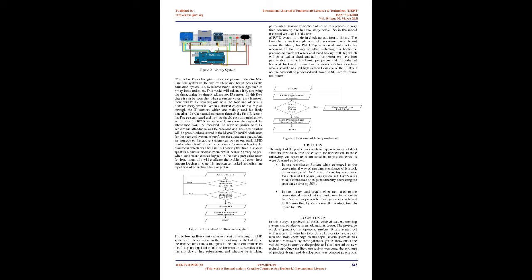Construction and working. The diagram tells us about the construction of the attendance system for in-time using RFID technology. There is an Arduino Uno as the microcontroller, having 14 digital I/O pins, which is shown in the diagram. Then it's connected to two IR sensors at pins 2 and 3 of the microcontroller, which will help in detecting objects. A micro SD card module at pin 4 helps in storage of data, which can be retrieved at the back end. A buzzer at pin 5 helps in giving intimation when students are late to class.